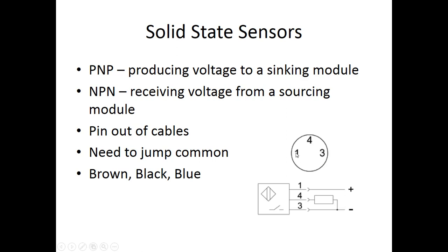This would be the right side of the cable if you were looking at it, and then you would run your fluke to the other end of the cable, and you'd look for the beep or the continuity. So sometimes people forget that they're looking at the mirror image. This is not the cable. This is the prox. The cable's the mirror image. We talked about how you can jump a common to do an input. You can't do that with an output.